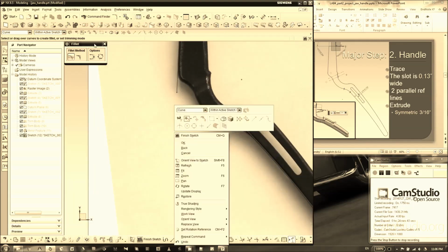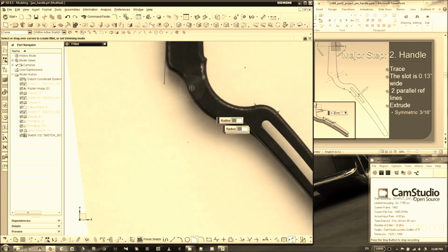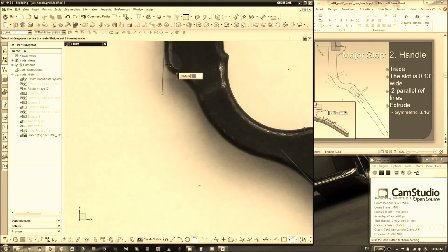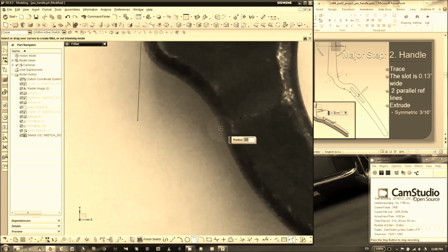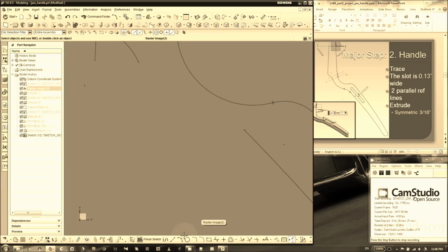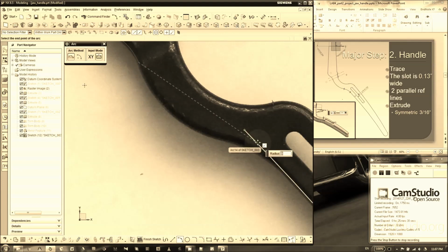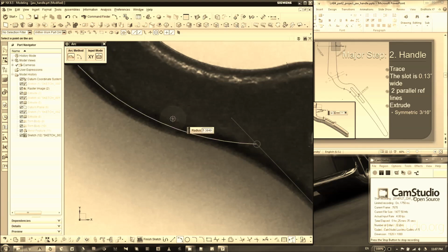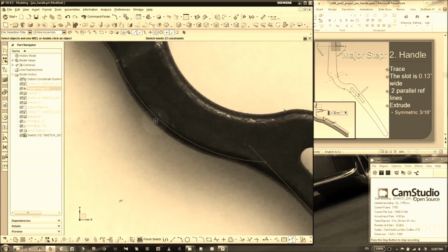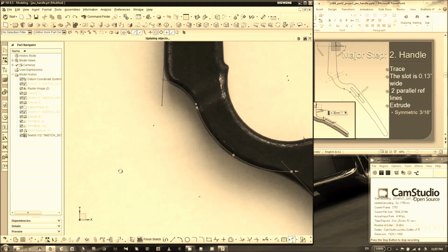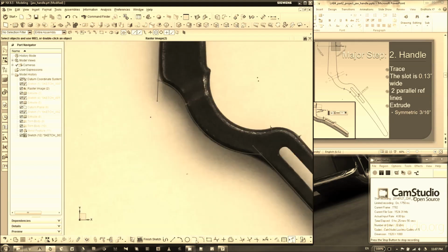Okay, so all we need to do is this section now. And let's see. We do have something like this. Okay, let's start from, you can see the transition between two arcs. So from here, 3-point arc, from about here to a point on the curve, and make it fit. Then come back and drag this a little bit, then come down to the bigger arc here, then it should be around here if you extend this arc all the way to this line. And yes, we do want a tangent, so let's drag this, or we can add it, make this point. Okay, alright, then fillet.